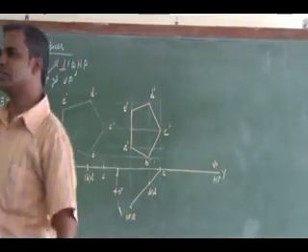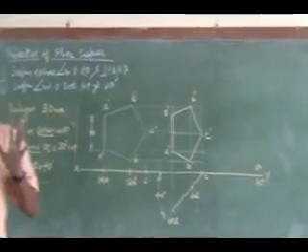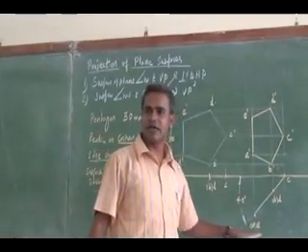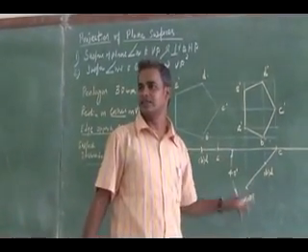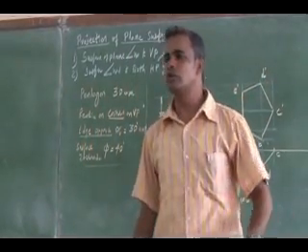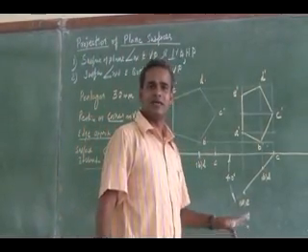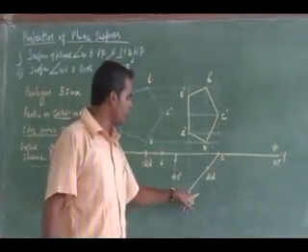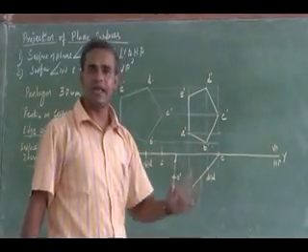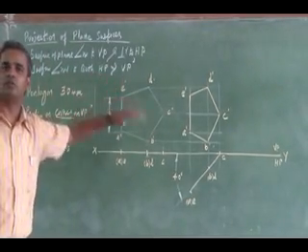So here, in this orientation, I don't obtain a straight line as a view. Why? In the previous problems I had a straight line as a view. Here, in this orientation, the final front view and final top view will be a pentagon shape, or some other shape. Why will I not obtain a straight line? Because the plane is not perpendicular to any of the planes. It is inclined to both planes.